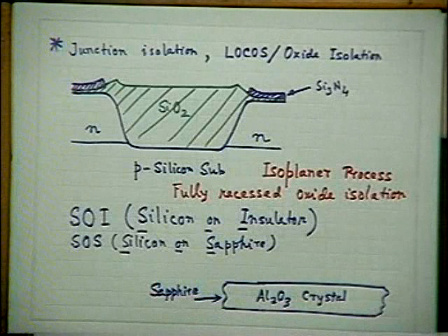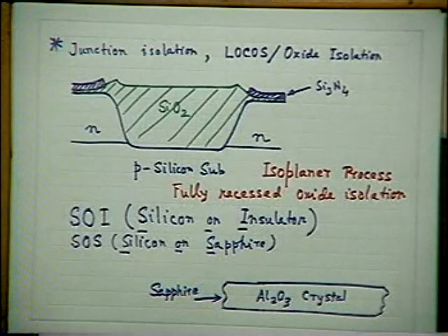But in our microelectronic applications, we are using sapphire as a substrate, a very expensive substrate. On the top of this sapphire crystal, you can grow an epitaxial film of silicon. That is why it is called silicon on sapphire. You can grow an epitaxial, crystalline film of silicon with very good lattice matching. This is possible. Certain crystal directions of sapphire and certain crystal directions of silicon match quite well. So you have to find out which two directions are okay for crystal matching. You can grow on this a silicon film, all right?